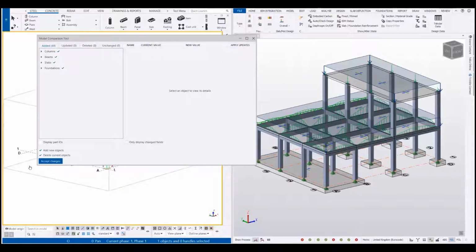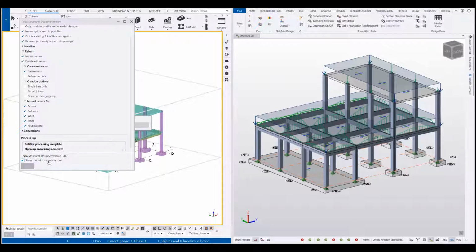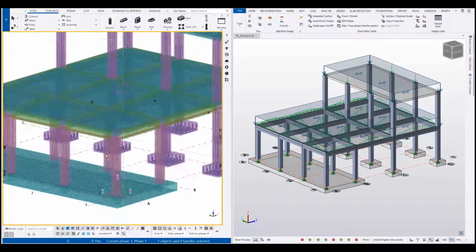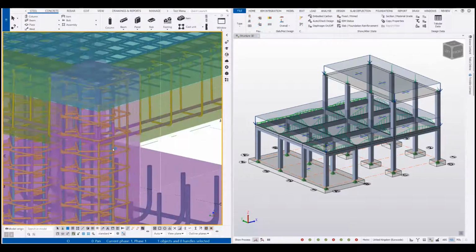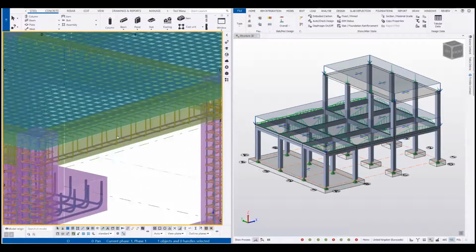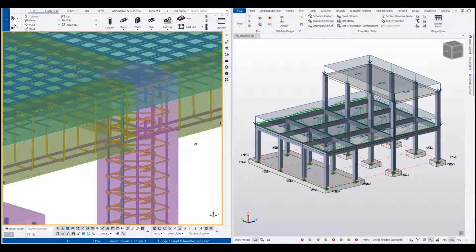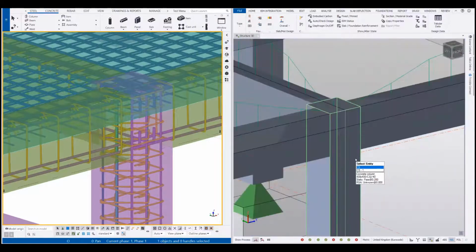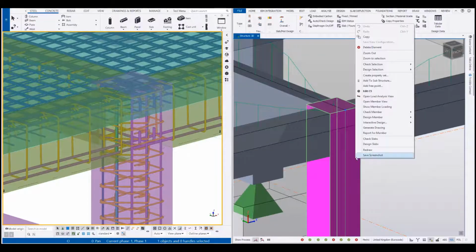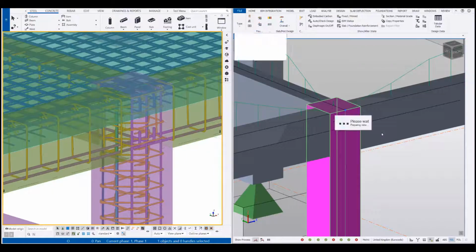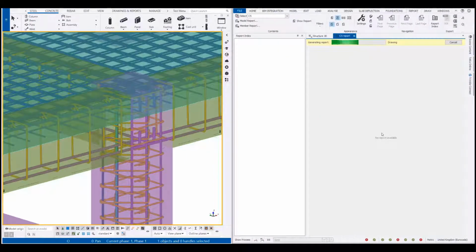Laps, cranks, layers and placement are identical to the output you get from the 2D drawings in Structural Designer, but now you get a collaborative 3D model for free. This transfer is harnessing the power of the rebar sets, meaning that you can rapidly change the arrangement of bars or the details to declash and provide high quality detailing with less effort and much less rework. With Tekla Structural Designer open, you can quickly validate the import against design ready for further work.